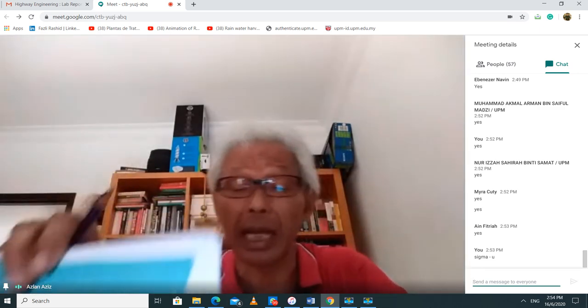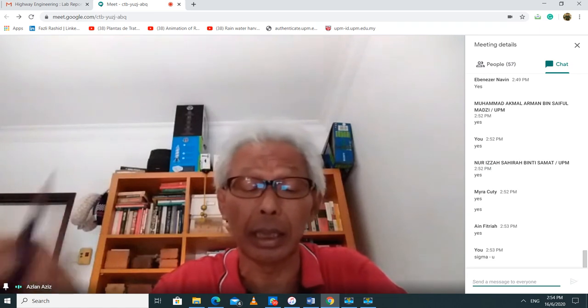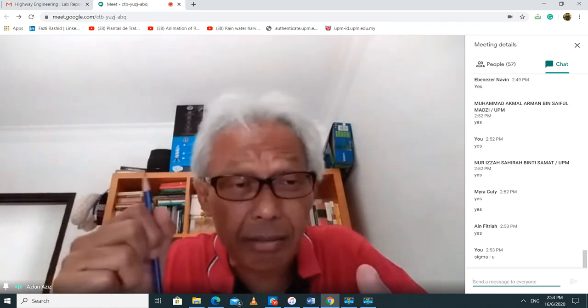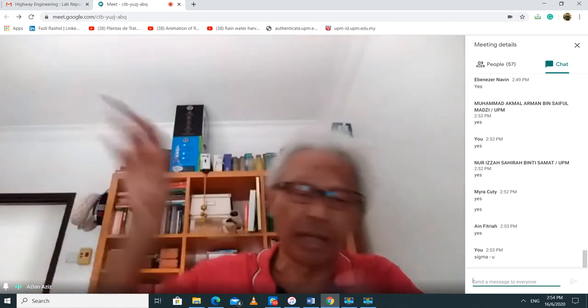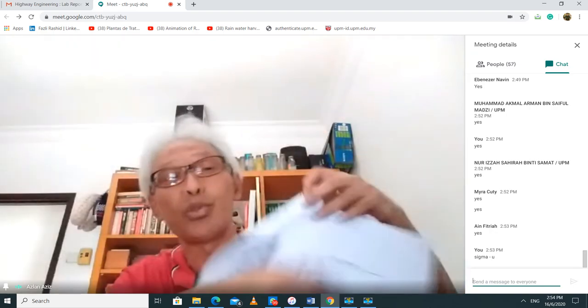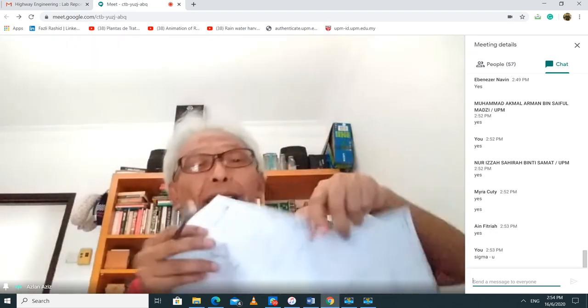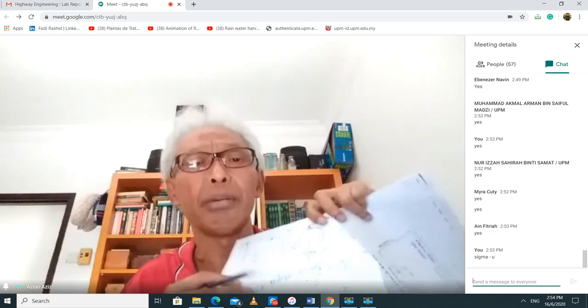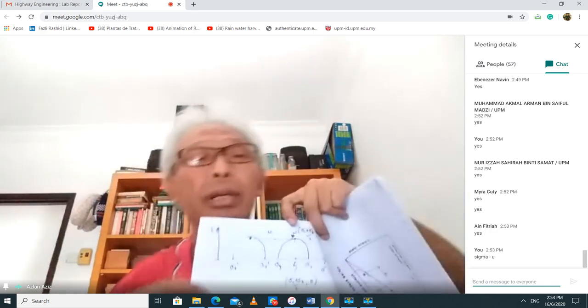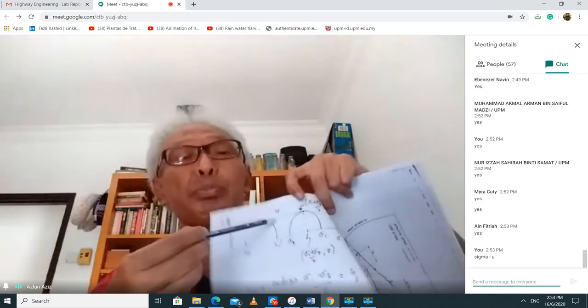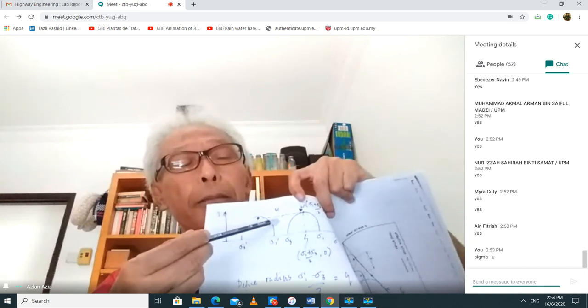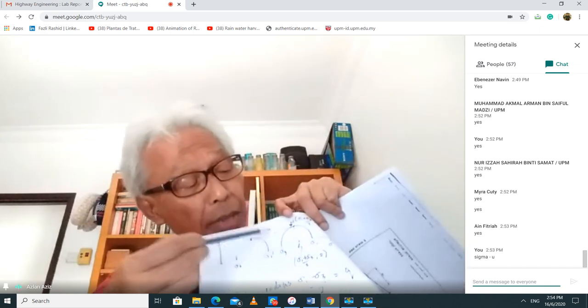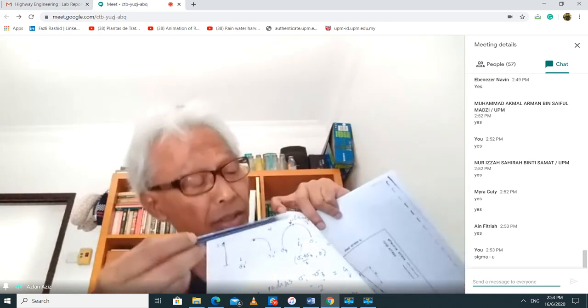Now I have the total stress. Okay, the total stress is on the right. Yeah, I have to show this. See, that's the big one. Sigma prime is sigma minus U. No, sorry, Fadli, U is pore water pressure, not sigma. All right, just by the pore water pressure. So Fadli is at least awake.